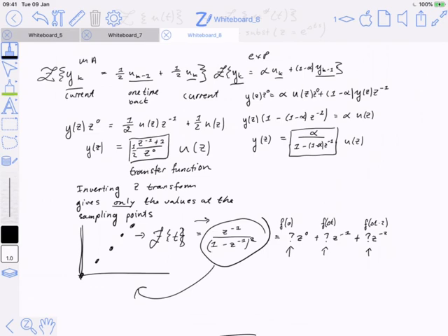The only thing you need to remember for Z transforms is that the thing so many time steps in the past goes to the thing times z to the minus so many time steps. That's all you need to remember. All the rest of the math is exactly the same. And I expect you to know that the transfer function is the same kind of thing that it was in Laplace, and that to find the output, you multiply the input with the transfer function and you invert.